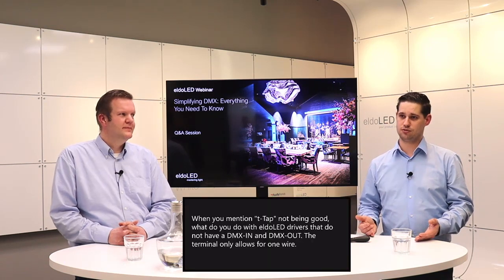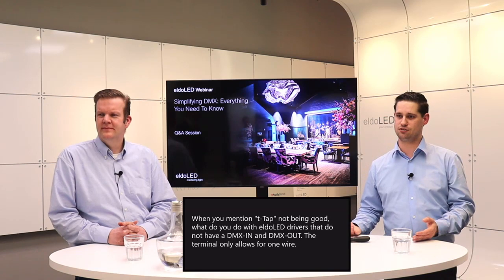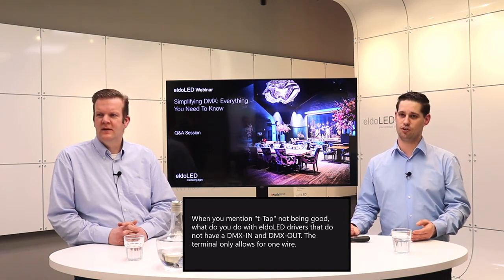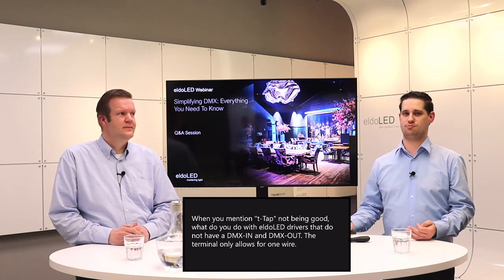When I mention a T-tap, it's not good. What do you want to do within eldoLED drivers to not have a DMX in and out? The terminal is only allowed for 1 wire. That's correct. And that's simply because of a space perspective.